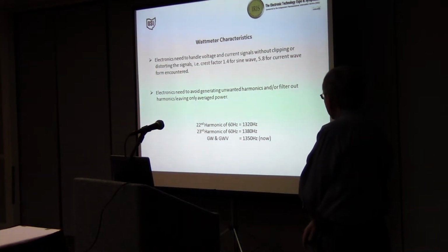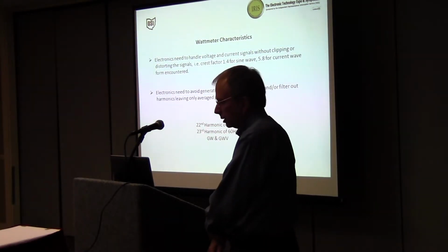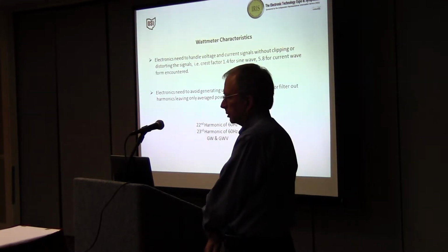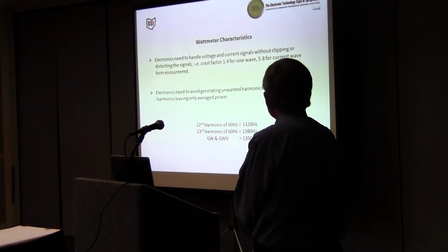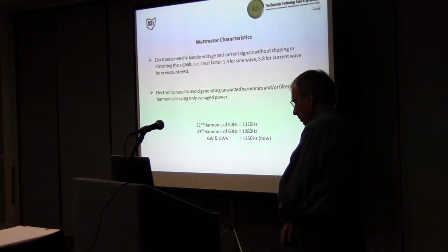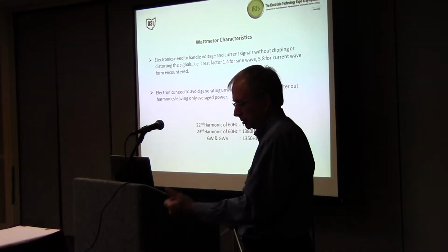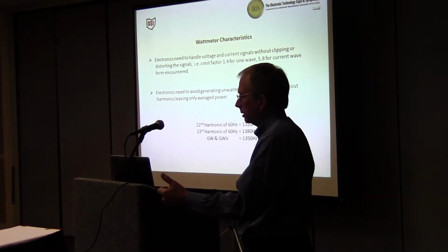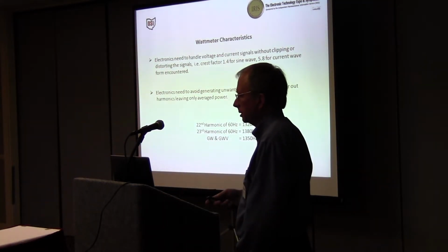We were working with some people building test stands for measuring washers and dryers, as I mentioned, that had inverters, and they called us up and said, your transducers are not giving us the right answers. So we went down to see what the problem was, and what we found was that they were measuring the current with a clamp-on ammeter, a true RMS meter. And they said, well, my gosh, I've got a 5 amp transducer, and I'm only putting 3 amps into it, and it's not measuring right.